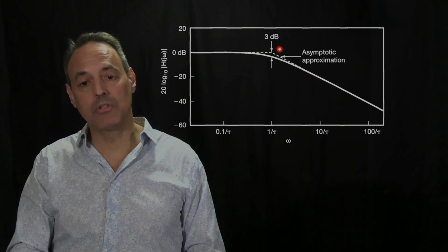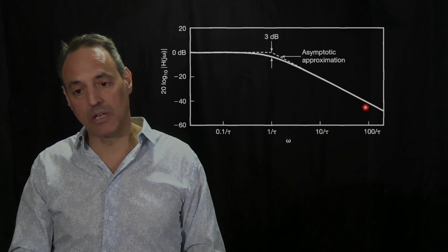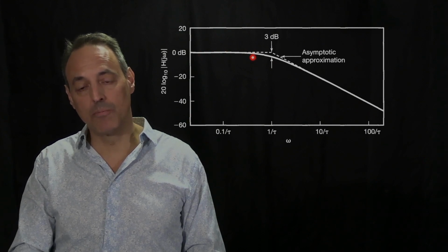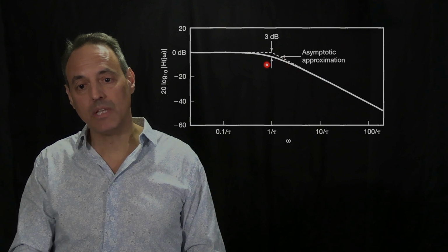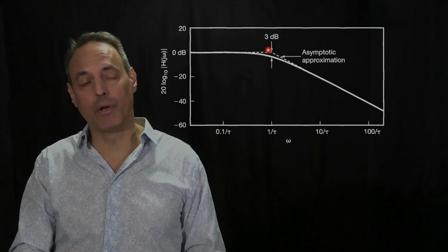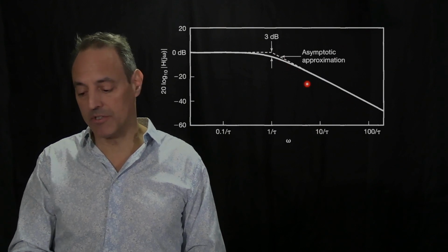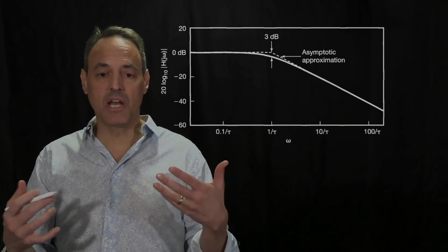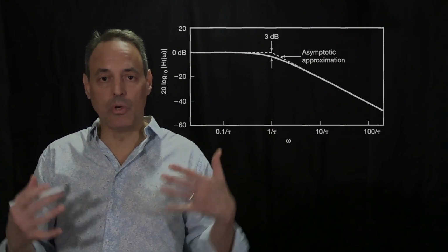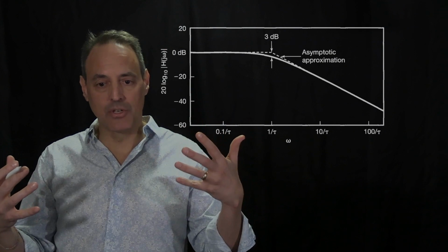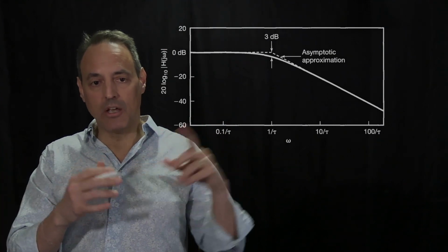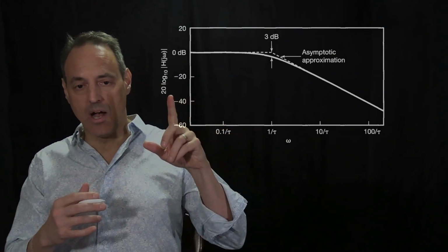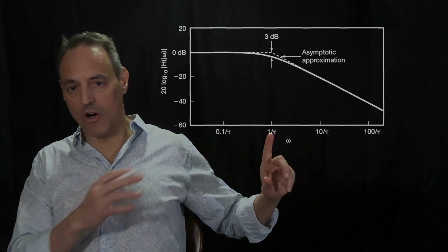And you have this interesting feature here where it's pretty flat. It takes a turn down. So it's linear here, slope 0, slope omega. And you get this fold over point here. We have approximations for both of these. And this is kind of what a Bode plot looks like. It tells you the response H in this log coordinate system as a function of log also of frequency over here.